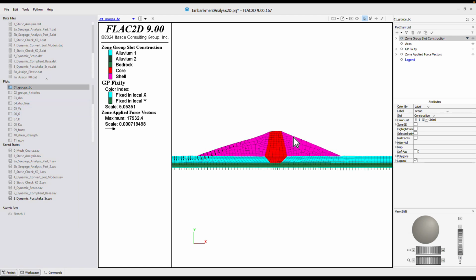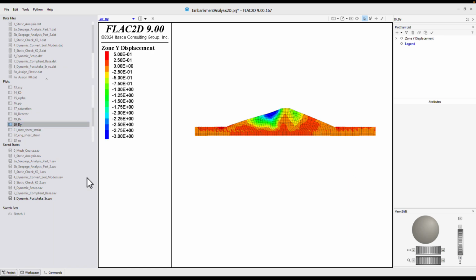Now, in this model, we can go down to displacement, let's go to vertical. Let's see, was there any impact? So I go back. I'm clicking back and forth, and although we have a much lower strength in that material, it is already deformed significantly. And because of that, the new configuration of the dam is such that there aren't additional appreciable deformations.